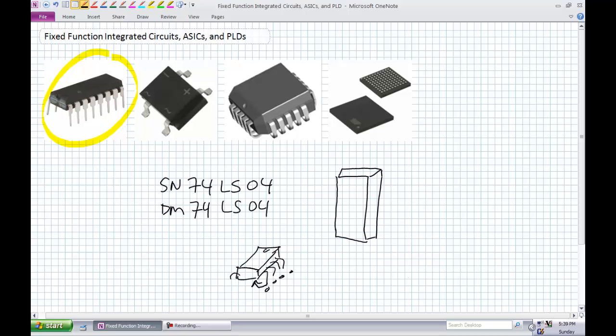Okay. All right, let's go back to pin numbers. There's always an identifier on chips. If they're plastic, unfortunately, they've got these little pore marks here. Those aren't the identifiers. It's a notch. You can even see that on this one. There's always a notch. Sometimes they even have the numbers on them. Okay, the notch, that's the top. This one, that's number 1.